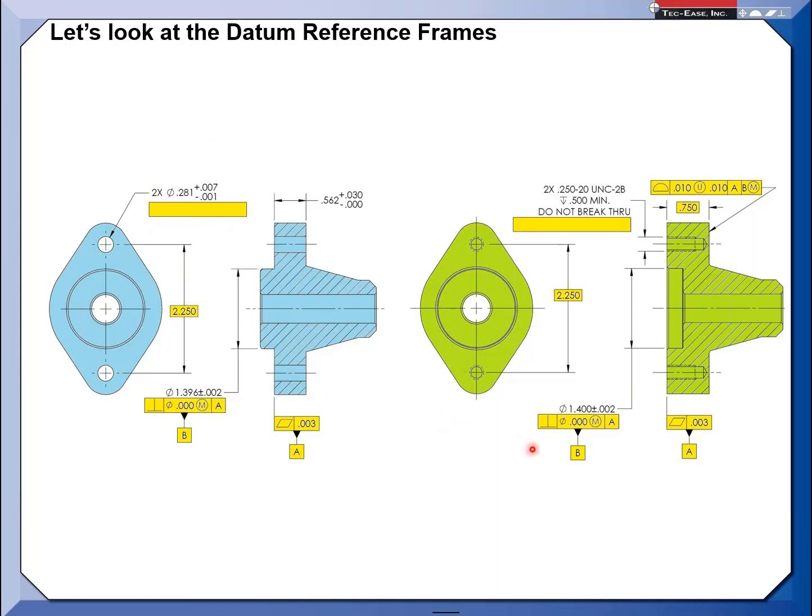Same thing when I hop over to the female flange, there's a datum precedence taking place here. Your primary plane here has a form control, flatness, on it. Now with flatness, you're going to get 2 parallel planes, and the points of the surface have to be within there. Like I say, you get 2 parallel planes separated the distance of what's given in the feature control frame. In the tolerance zone, anything goes as long as the points in the surface are within that.